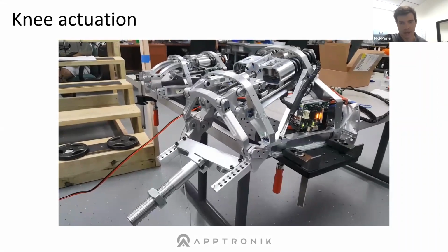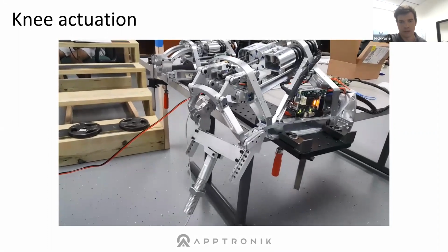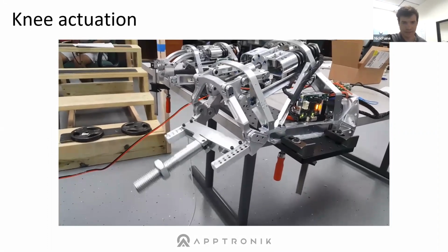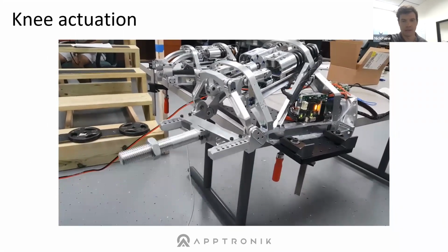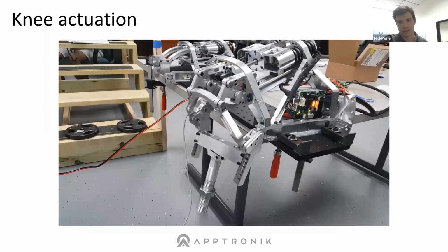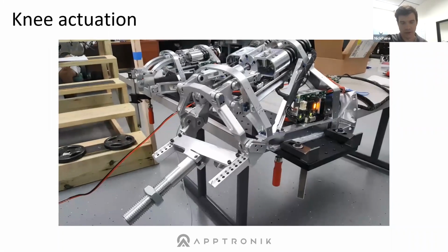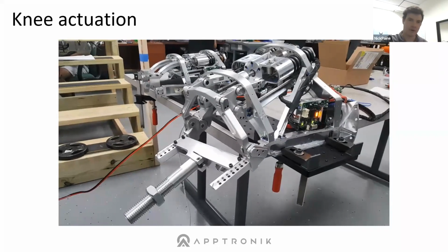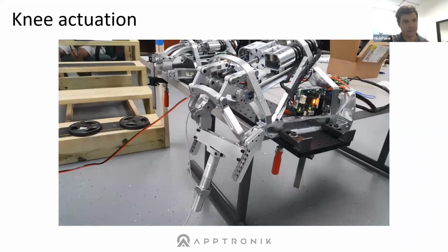This video is just showing that mechanism moving around. So you can see here the motor's driving this linear stage, which then is attached to some linear rails and a linkage that transmits that linear motion into a rotational frame. And then the structure wraps around the human to keep a low profile.